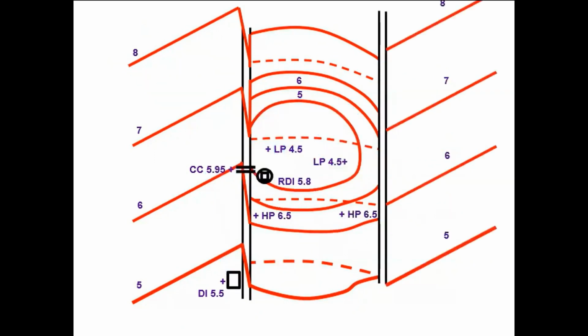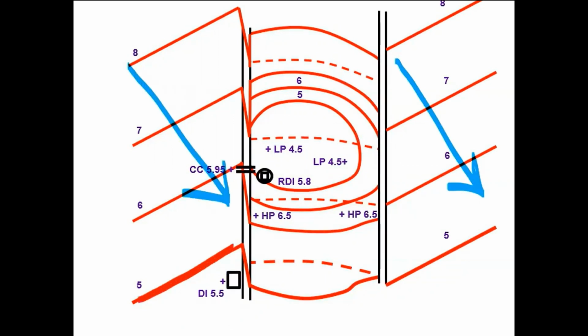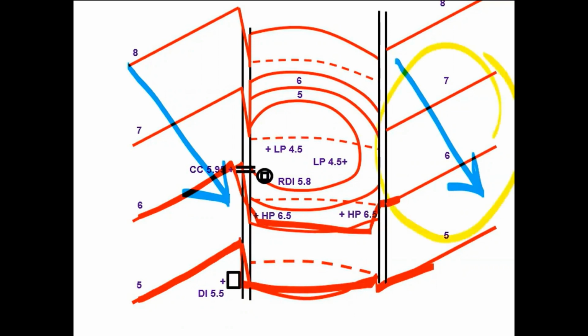And then finally, we want to show what it looks like if we have a parking lot on both sides. We're not really worried about the drainage of the parking lot on the downhill side because it's flowing away. We're only worried about the drainage on the uphill side. And the contours, of course, will connect over, as you've already seen, in a fairly straightforward manner. So the system is basically the same, although we have this extra parking lot over here on this side. You're going to be designing the system for that extra parking lot downhill.